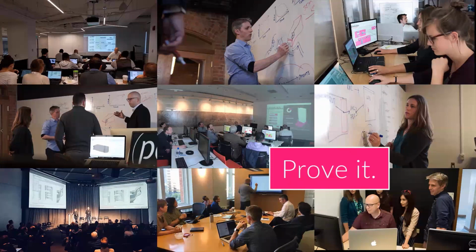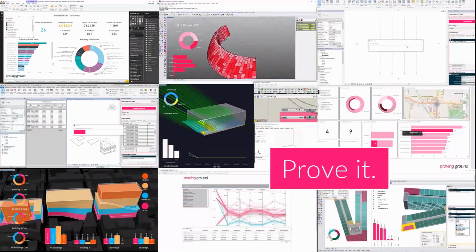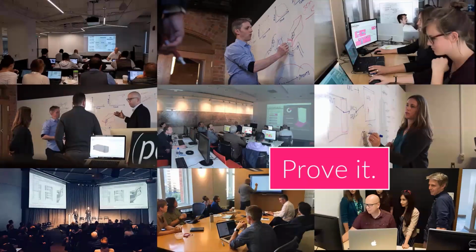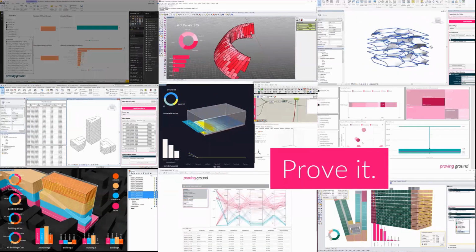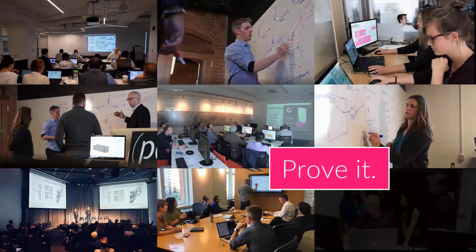Yeah, that's actually interesting. So the idea that you might have a family in Revit 2022, and you could kick that over into Rhino, and we're bringing over properties with that object, and then reconstituting that as a family in another environment. I would say it's not going to be perfectly seamless, but it certainly offers an opportunity to make the family object with its data interoperable to some degree. You start to get into some interesting edge cases going from a BIM element back to a geometry element back into a BIM element. There might be some wonkiness to sort out there, but it seems quite possible.